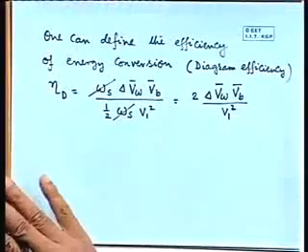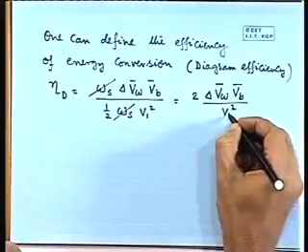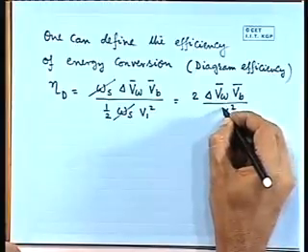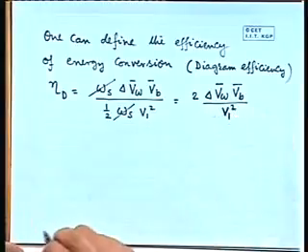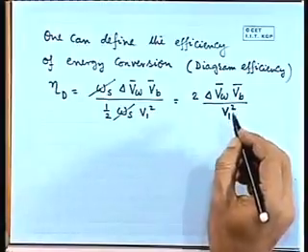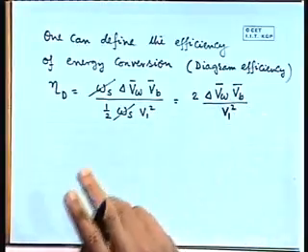Now, the question is how these design parameters can be selected so that we get maximum efficiency out of our designed turbine. Probably at this point we are in a position to decide that at least partially. Here you see that we are getting two velocity components, one is V1 and another is Vb.